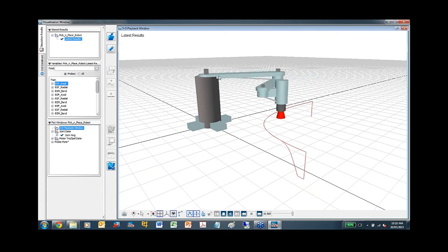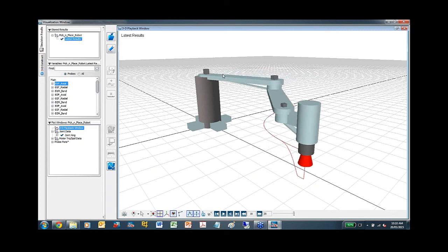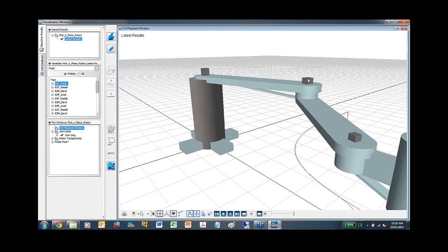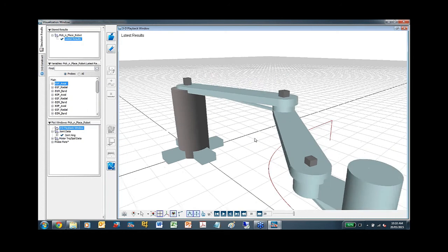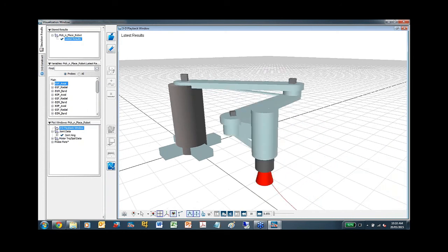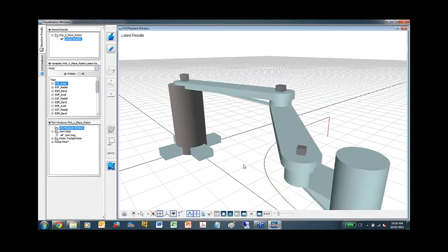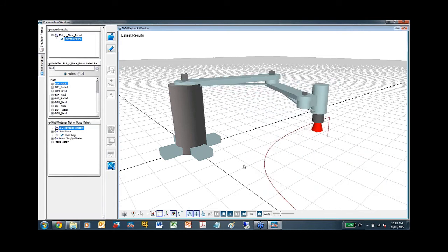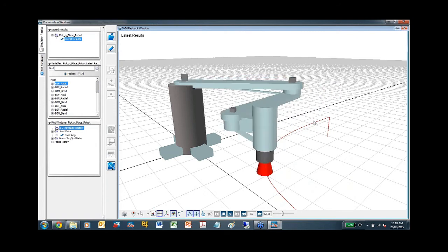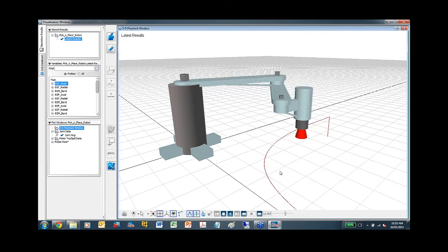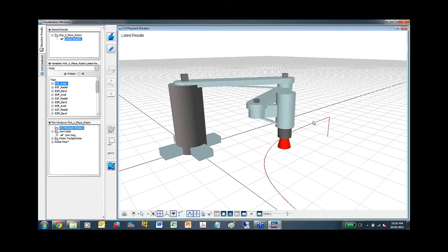For better visualization of what these motors are doing, I have put these components on top of these revolute joints. And as you can see, if I rerun my animation, these motors are spinning at the highest speeds. With the help of the high ratio gears, we can achieve this accurate trajectory or path tracking at the end effector.